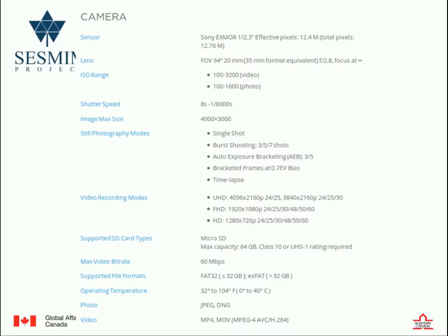So the aerial software, the processing software, like Agisoft and Open Drone Map, requires your camera lens focal length, okay, which gives you the field of view, all right? So that is the geometry of the imagery. It's very important. So you need to know the focal length of your camera.